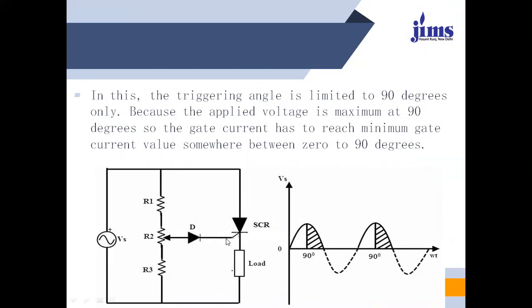So it works as a unidirectional gate current, and the SCR remains off until the current flowing through the gate is more than the latching current. It will turn off the device whenever the current from the supply through the SCR to the load and back falls below the holding current. Then the SCR will turn off.